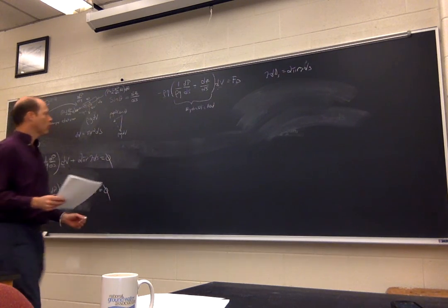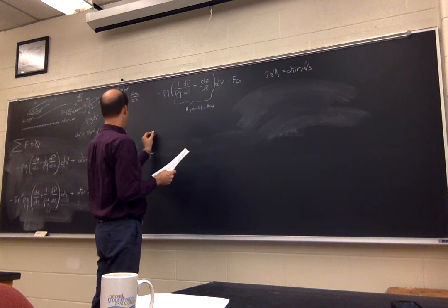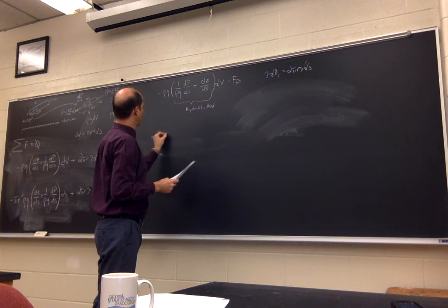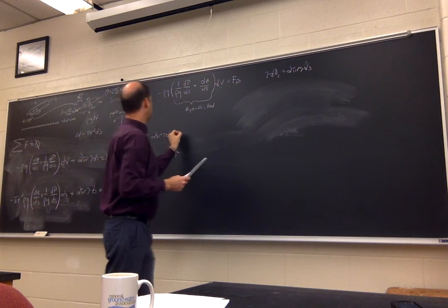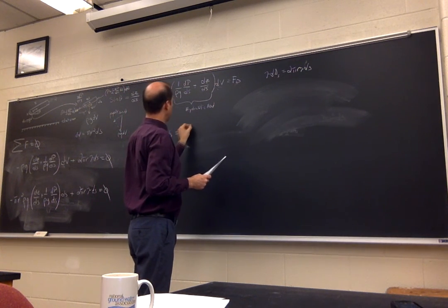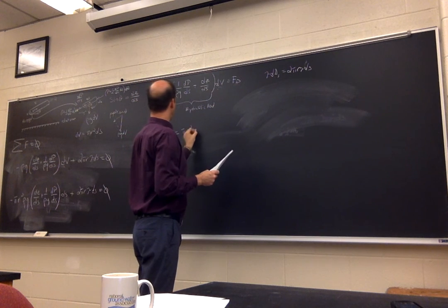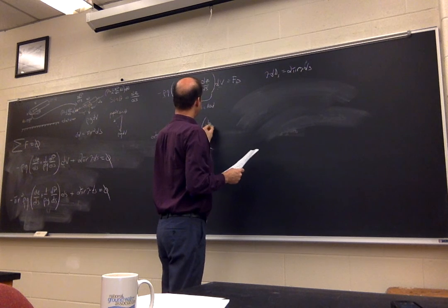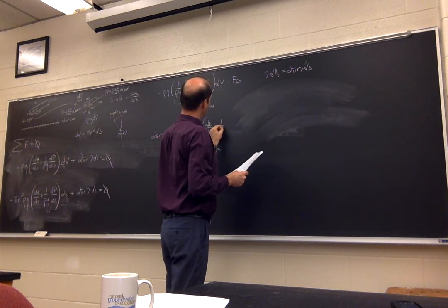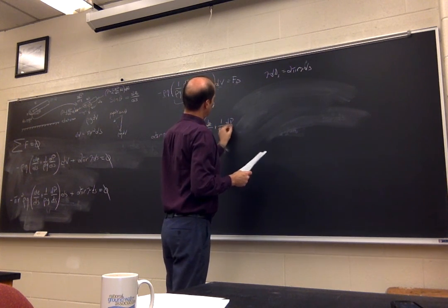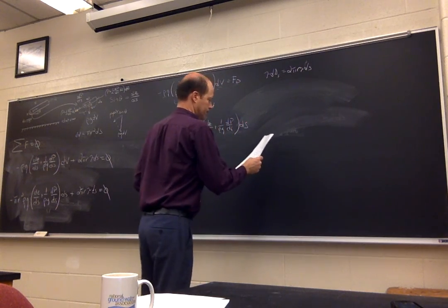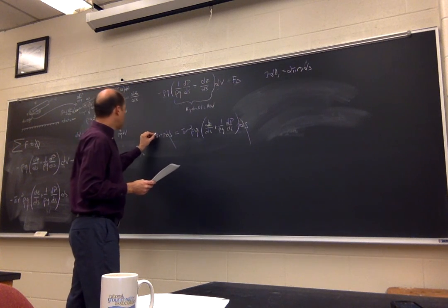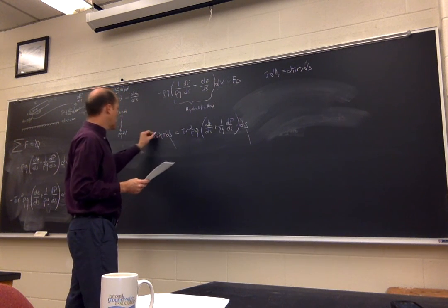The first step is 2 pi r tau ds equals pi r squared rho g times dz/ds plus 1 over rho g dp/ds, times ds. The ds's cancel. One of the r's cancels.